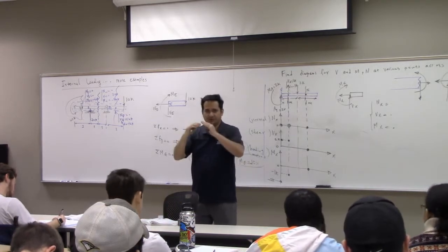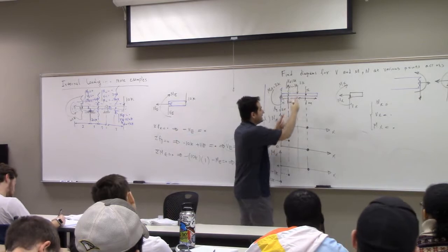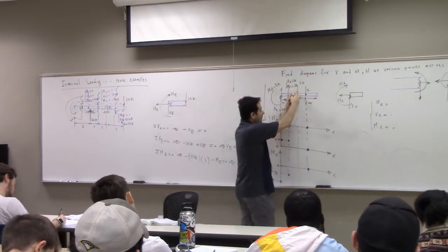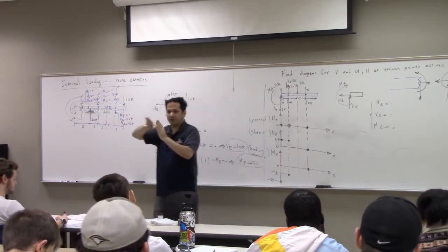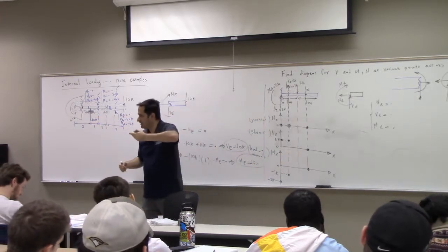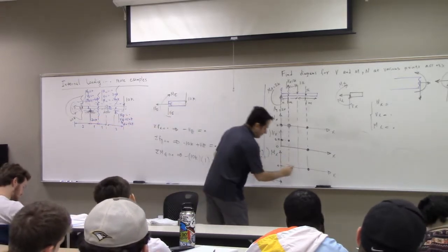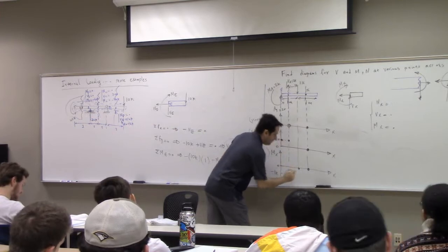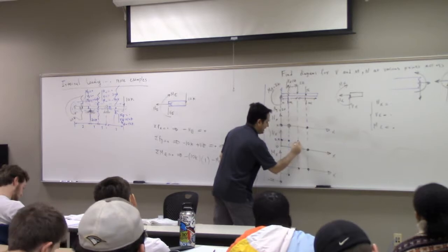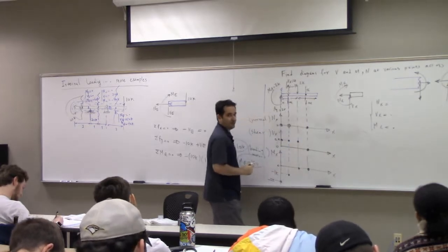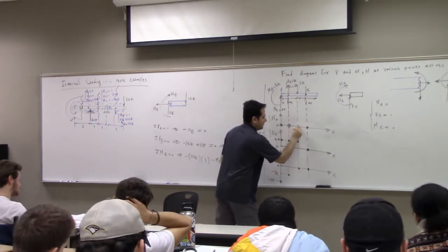You have a discontinuity, right? But if you take an infinitesimal piece from the right to the end, then you have no forcing on the system. So the bending moment is 0. So you have another point here. What about the shear? Shear is still positive 2K. And the normal force is still 0.